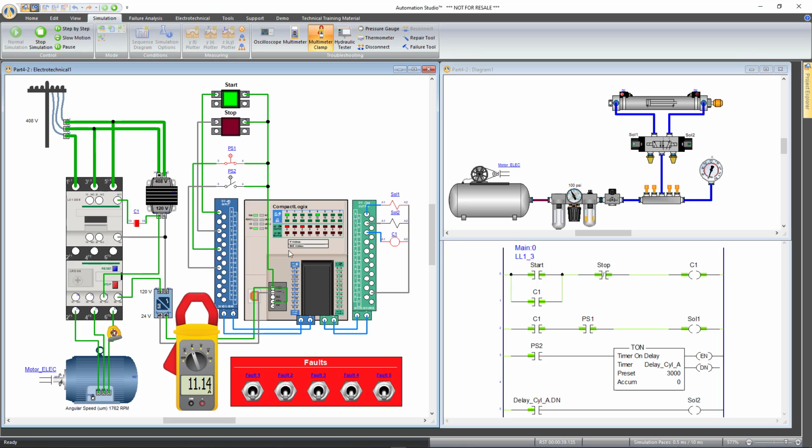But just so we see what's going to happen when we trip fault 5. I trip fault 5, compressor jam, and then my overload trips right away. So what's happening? If I just reset my overload, right away it goes really high on current and trips again. So what could cause this issue? Then I need to go through the system and try to figure out what could be the problem, and so on. Okay, and then if I take it off and I just reset my overload, boom, everything works fine again.